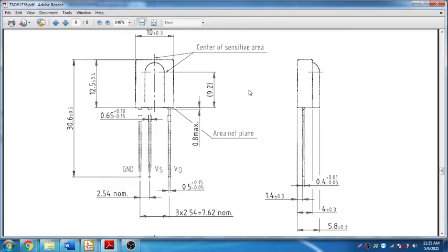Just look at now here what you need to see is that dimensions. Okay, so what I am so keenly interested in is this particular dimension. So we will need to fix up this dimension. So this 7.62 is the pin, so we can say around 10 mm as our width here of the polygon, whatever rectangle that we draw.